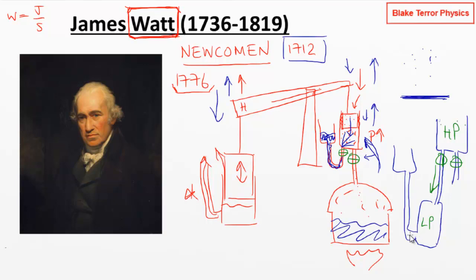You then spray the water into the condenser to condense the steam, which creates an even lower pressure, which then creates low pressure in the piston with the same effect as before, but the piston still remains hot. The loss of the energy to the surrounding material is happening down here in the condenser. So there was a big energy saving in this, and it pretty much doubled the efficiency of these steam pumps, because you didn't have to keep on reheating the piston all of the time.